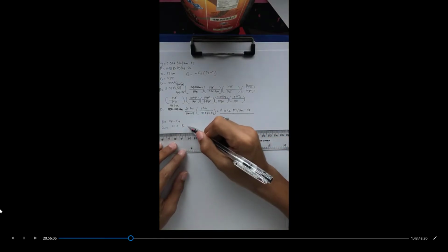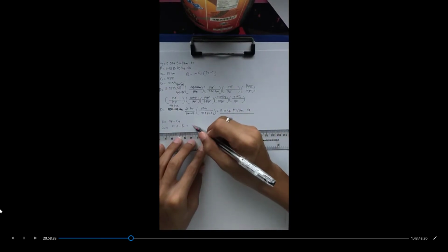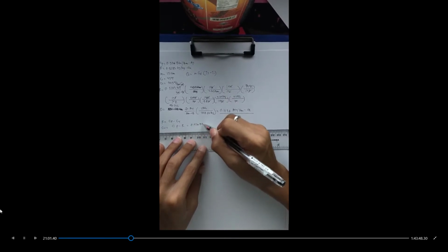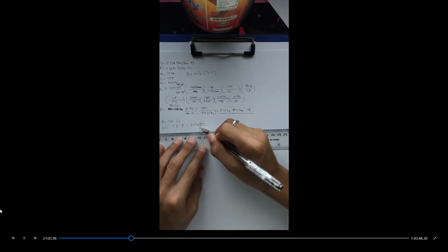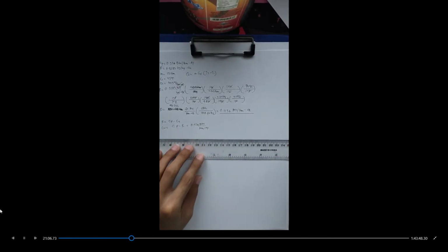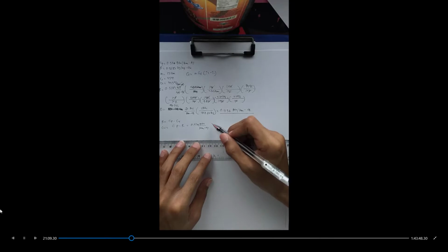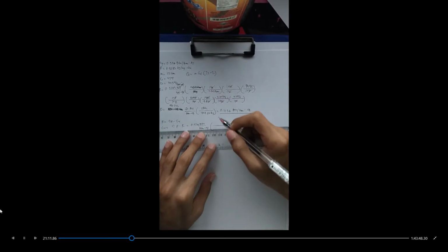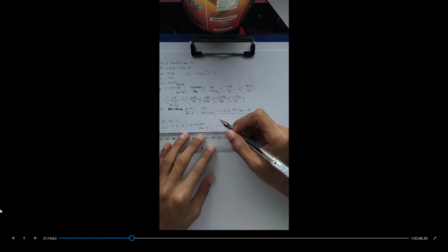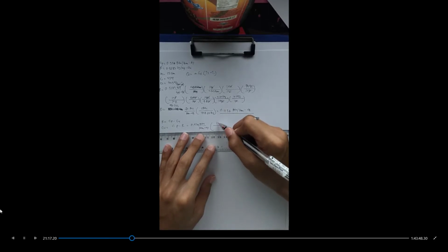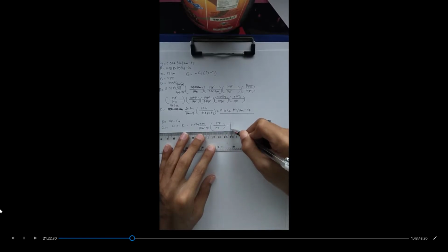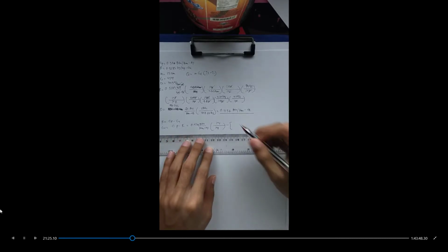Now, by substituting the values, my Cp is 0.526 BTU per pound mass degree Fahrenheit, and then we need to convert degree Fahrenheit to degree Rankine. By using the concept of temperature difference, 1 degree Fahrenheit here, 1 degree Rankine at the bottom, and then minus our gas constant in the English system, which is 0.1237 BTU per pound mass degree Rankine.